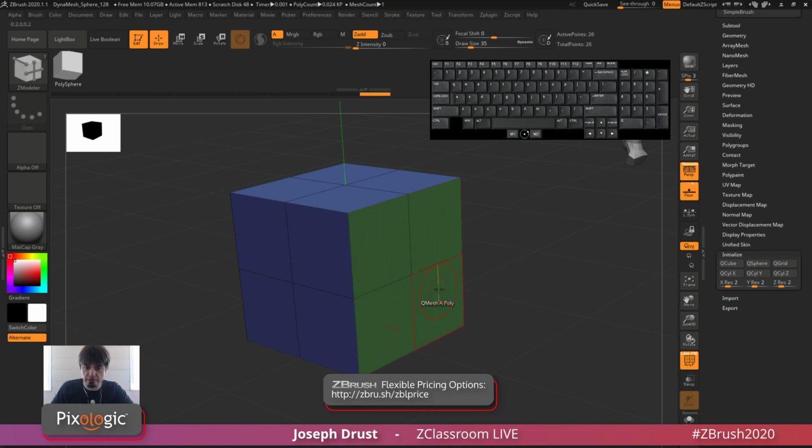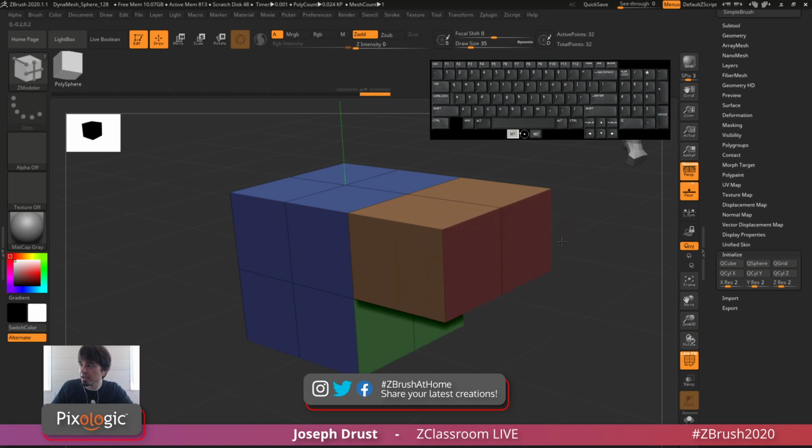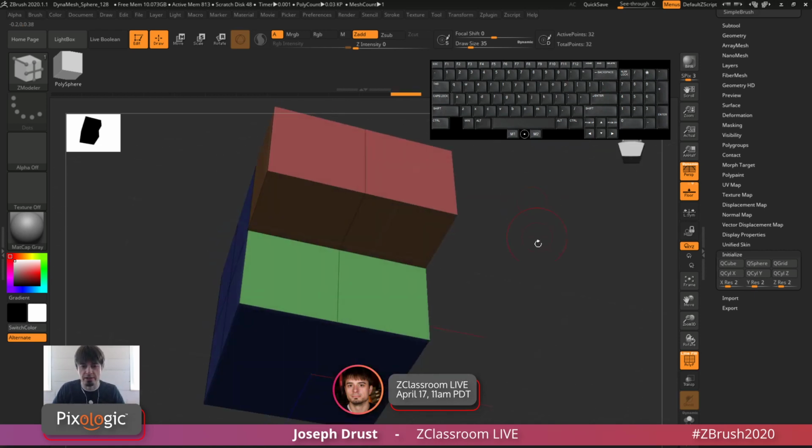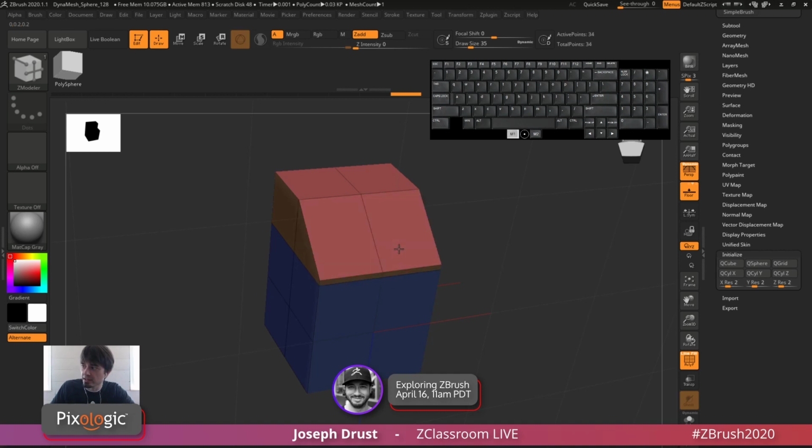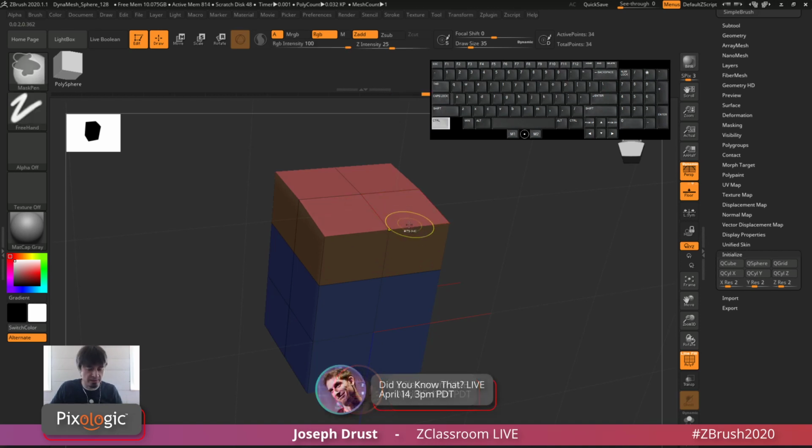What this allows you to do is come across your model, and if I use this QMesh action on this face here, I can just come through and add geometry. I'm just taking that face and basically extruding it out. Now the QMesh action is a smart extrude, which means it's going to perform a snap option as you do this action. If I come across this poly down here and click and drag, you're going to see as I'm dragging up, it's going to snap. This is going to weld to that other piece of geometry, and then I can control the angle from that. I'm doing this with symmetry at the moment, so it's doing both sides across here, but you can see how that's snapping there.